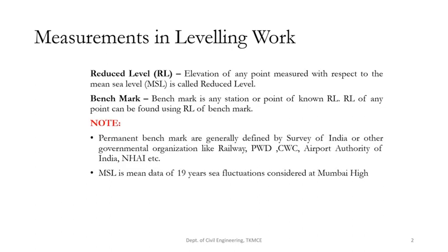And you can see the benchmarks are generally defined by well-established organizations like Survey of India or other organizations like the Indian Railways, the PWD (Public Works Department), Central Water Commission, Airports Authority of India, National Highways Authority of India, etc. We can start our survey work with respect to those established benchmarks. And the mean sea level datum in India is taken from 19 years of sea fluctuations considered at Mumbai High. Everywhere in India, we take the mean sea level with respect to a place called Mumbai High in Maharashtra.